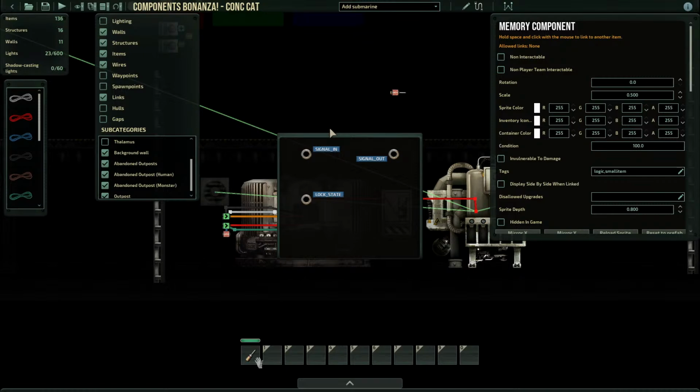So a 0 signal can overwrite other signals, right? So if you have a 1 going into, say, the signal in port of an AND block or a greater than block, that 0 is considered in the greater than, and it's considered as part of the logical comparisons in terms of true and false. If you send the 1, that 1 will persist. So if you send an impulse signal to that AND component, you don't have to sustain it as long as nothing is coming in behind it to overwrite it.